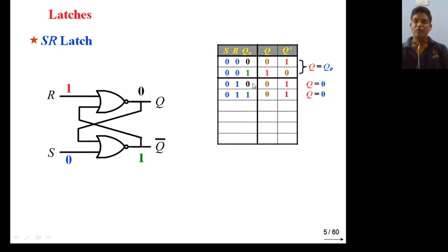And from these two you can directly apply the shortcut method, okay. You do not need to determine this every time. This is 0 1, this is 0, this is 1. Now you know the property of the NOR gate. If any input is high, the output will be low irrespective of the value of other inputs.